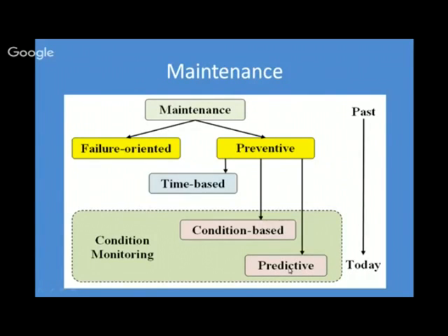more used. In predictive maintenance, we have sensors being installed on the motors or drives. Those sensors will directly give us the key features of the machine, like vibration or noise or the current that is being used by the motor.